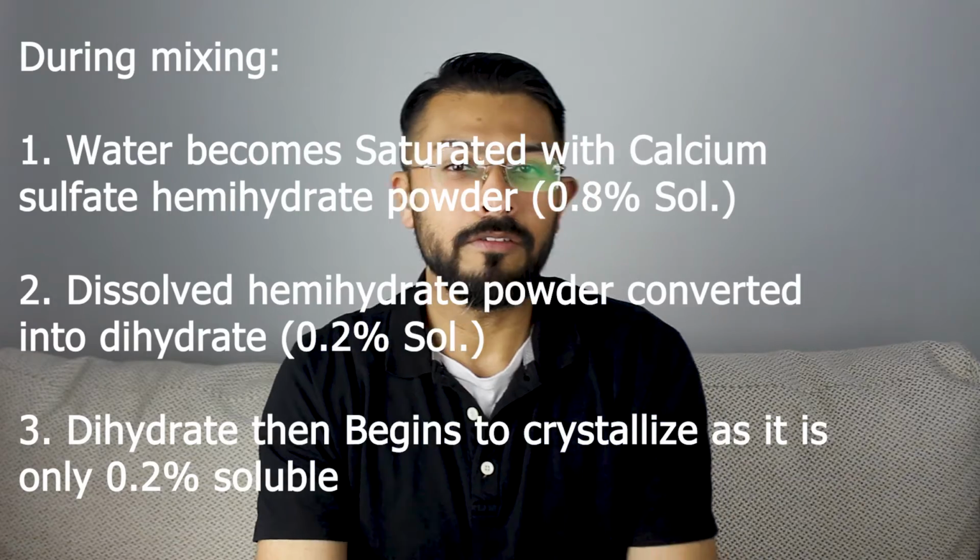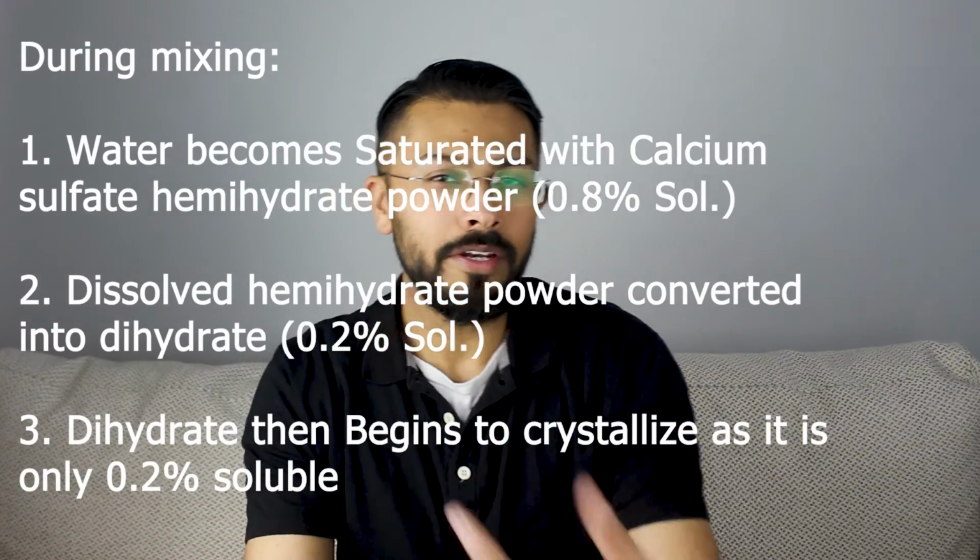The crystals of dihydrate are spherulitic in nature and grow from specific sites called nuclei of crystallization. These may be small particles of impurity such as unconverted gypsum crystals within the hemihydrate powder. If a thin mix of a material is used containing more water than that indicated, the formation of a supersaturated solution of dihydrate is delayed.